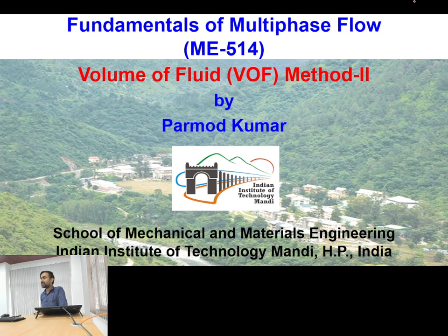Here we have two steps. In one case, depending upon the value of the volume fraction, we construct the interface. So we have discussed already the interface reconstruction techniques, and then in the next step, because we also have to show the temporal evolution of the interface, we do advection of the volume fraction field.